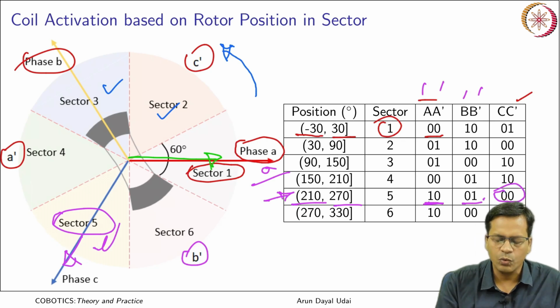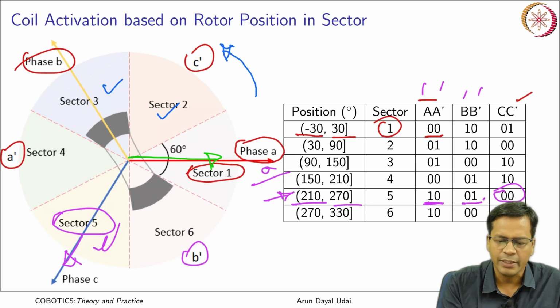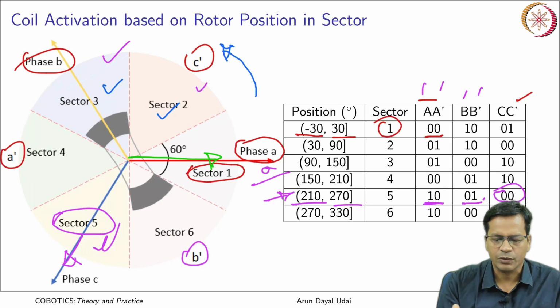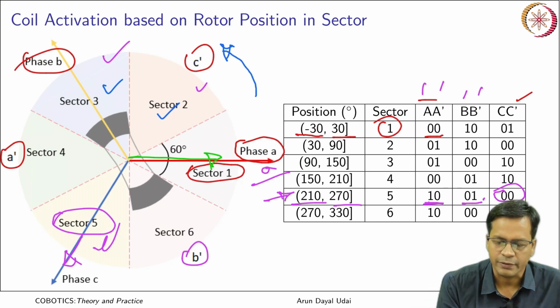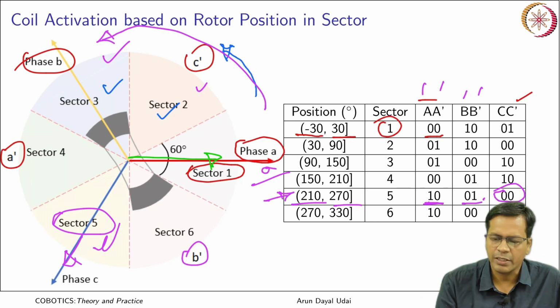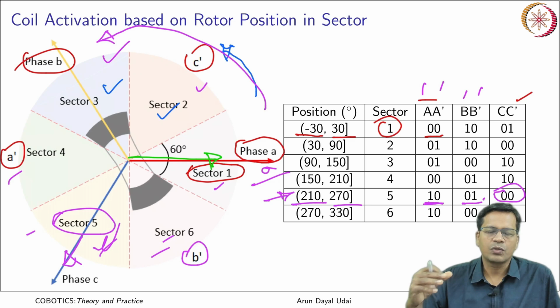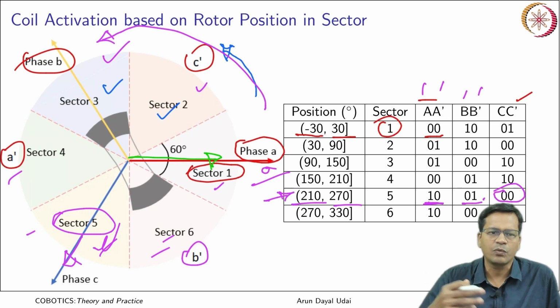So what you do actually, wherever your rotor is located, in any of the sectors, you energize the next two sector coils so that it gets a pull and finally it moves in that particular direction. Okay, so in this case it will move like this. In order to rotate it in the opposite direction, the reverse has to be done. If it is here, you switch on 6 and 5. If it is at 6, switch on 5 and 4, likewise. So the coil can be energized based on whether you want to take it in a clockwise or counterclockwise direction.